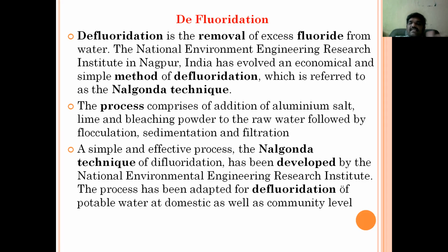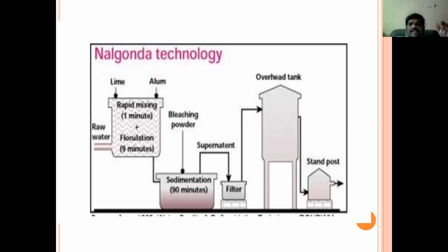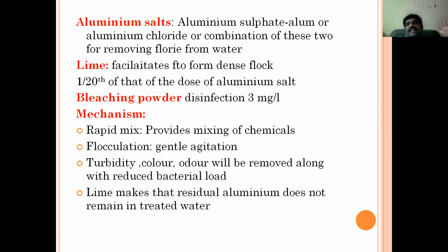We have just seen the technology behind this Nalgonda technique: 4 steps, flocculation, sedimentation, filtration, and disinfection, that means bleaching powder. It is highly efficient in removal of fluoride concentration in the water.